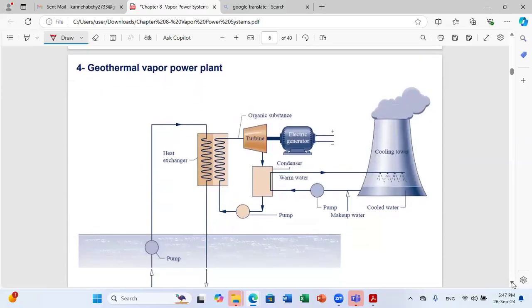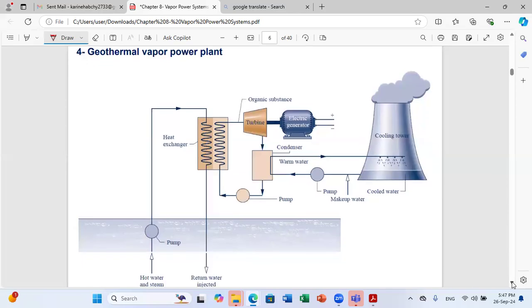And we also said that it's possible to use geothermal sources for our heat input. So as you can see, always the same concept. What is changing is just how we are getting heat in this heat exchanger. A possibility in geothermal application is to extract hot water: when you go deeper and deeper, at deeper levels the temperature is more stable, so you can reach high temperatures.